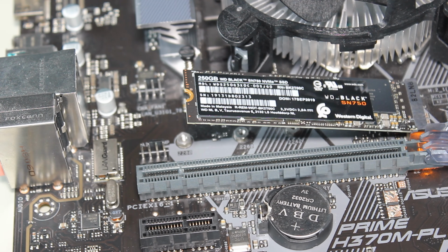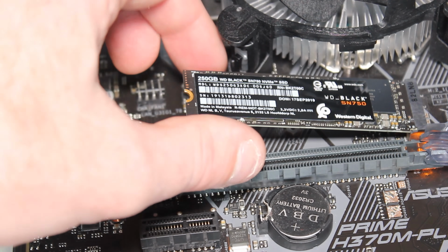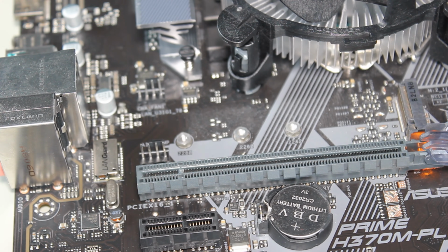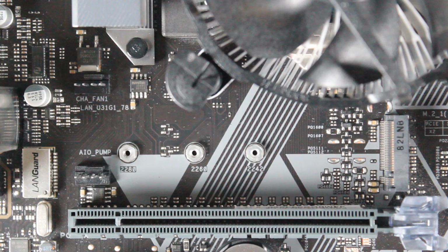Once the screw is removed, it is just a matter of pulling the M.2 SSD out at a 30-degree angle. If all goes well, it should just pop out. Don't lift it straight upwards as you risk damaging it. On this motherboard, notice that it supports 3 different M.2 form factors, these being 2280, 2260, and 2242. The standoff needs to be installed for the form factor that you are using. In this case, the M.2 SSD was installed without the standoff and thus appeared to be at an angle.